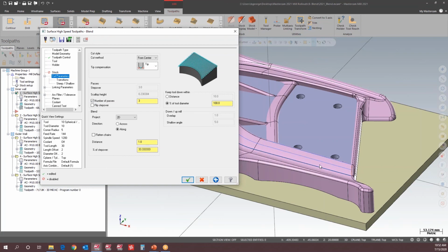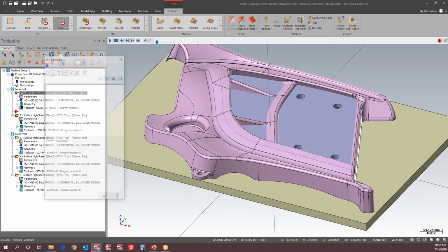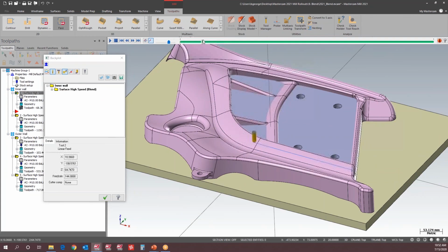This will be an awesome toolpath for that, because you can tell it, okay, I only want you to do 3 cuts up that blended surface. So if you take a look at that from center, all it's going to do is start at center, take 1 cut, and then 2 more cuts. Those are the 3 cuts that we defined.